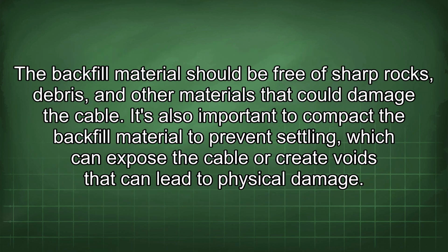Ninthly, proper backfilling is essential for protecting buried cables. The backfill material should be free of sharp rocks, debris, and other materials that could damage the cable. It's also important to compact the backfill material to prevent settling, which can expose the cable or create voids that can lead to physical damage.